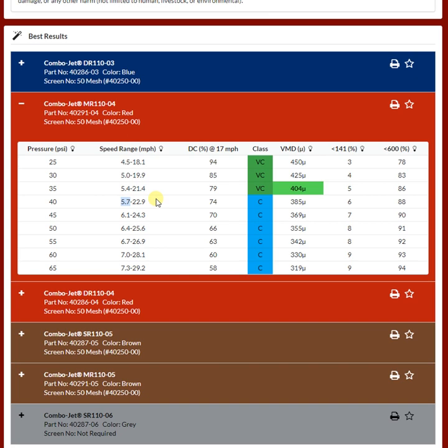So what you can end up doing is you can end up getting checkerboarding. Again, not typical for most applications, especially if you've picked the nozzle correctly for your application requirements. But that is the penalty to having a duty cycle that is too low. In this case, though, being above, just at 74%, no issues there. We're happy because, again, we have 26% more flow capacity we can put out without changing a thing.